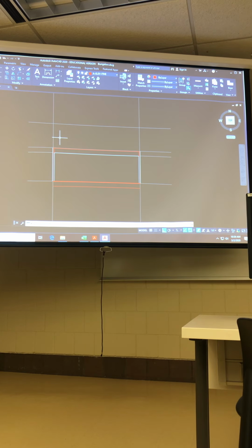So on top of my truss, I have roof sheathing. And if you remember from the description in the handout, that roof sheathing is 5/8 of an inch in thickness, right? On top of my roof sheathing, I'm just going to offset a line 1 inch, which is kind of the thickness of all the shingles and stuff that's going to go on top of that. It's not a precise dimension. I don't really care. It's just an approximation. So I'm going to finish up by drawing my sheathing and then my roofing material on top of the sheathing. And then I'll be ready to start mirroring things over.